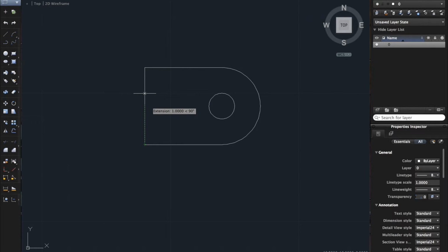So what we're going to do is we're going to go to the midpoint, bam. Oops, I didn't put the circle, okay. There, we're going to click the midpoint, and because we're doing 1 inch, we're going to do 0.5, which is half an inch. Remember, we're in inches, so it's 0.5 an inch. And then there, that's our circle.